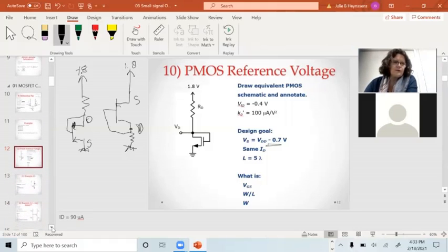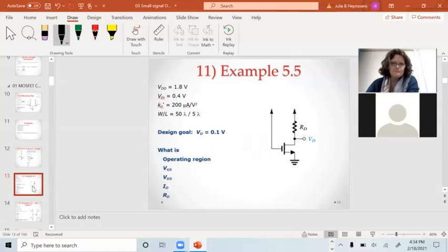That current transistor on the diff amp is pretty much used to bias it, to set the amount of current for the whole circuit. And a lot of times what you want to do inside an integrated circuit is you have several of these op amps inside there, and you want the currents to be matched across there. So you would use that current mirror, the 2 transistors that we looked at yesterday, to match the current from one op amp to another. Fairly easy to do inside an integrated circuit. Okay, I'm not going to talk about that circuit again. I did that in the last class.